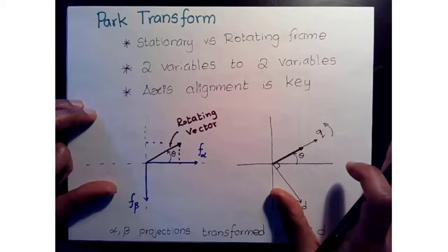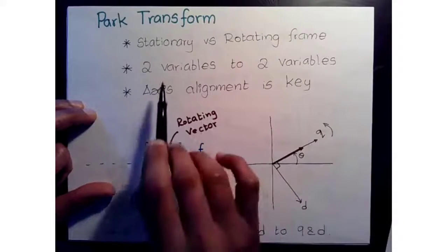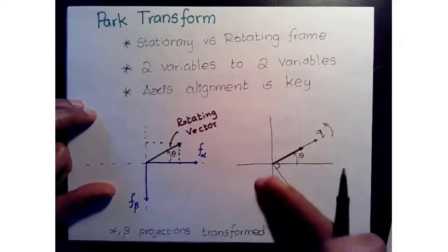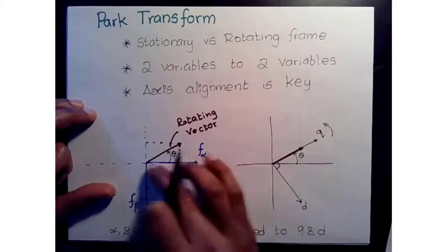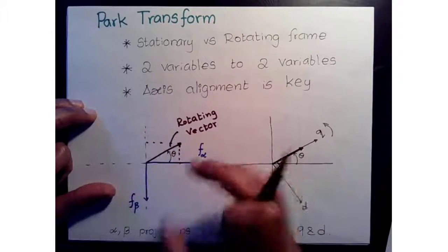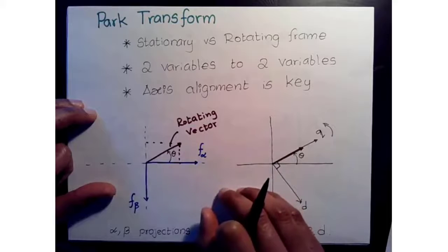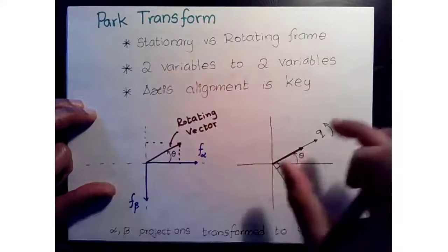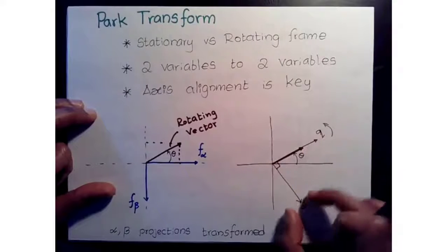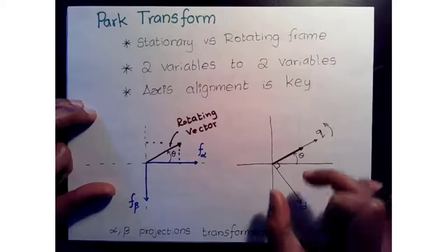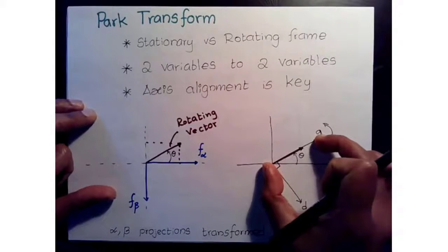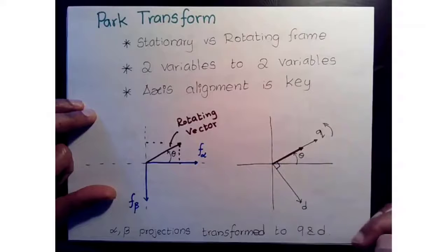What our goal is, at least. Now since we have alpha beta here, it's a plane, right? You need two coordinates or two measurements to determine the full vector without loss of information. And even in the new axis system, you still need two measurements: the Q quadrature component, and the D direct component.